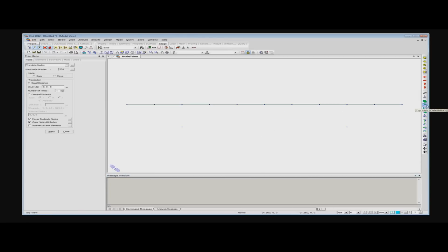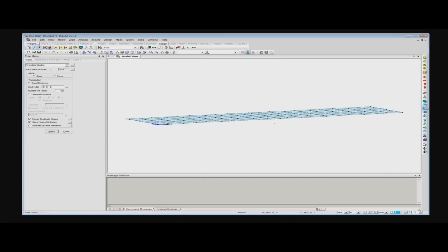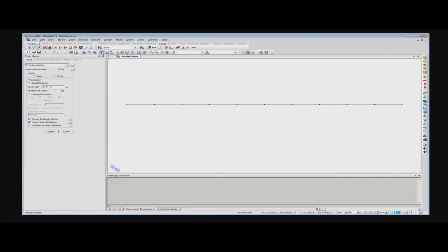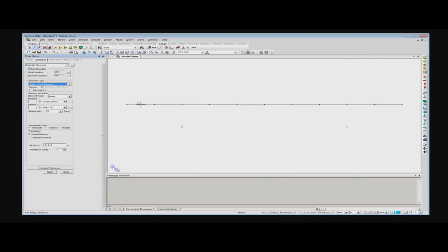So technically you can switch your view and see how it works. So in isometric view we have that. Okay, so it's very easy to generate those piers. We have two piers, so simply we can select these two and right click, go to the element, extrude, and then simply extrude them. Equal distances, -20, and apply. Oh, I selected the wrong sections. And select previous and apply.